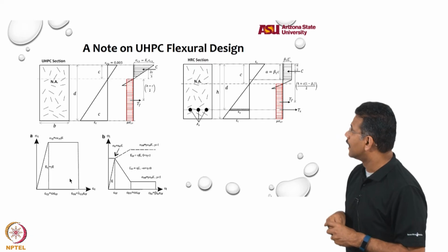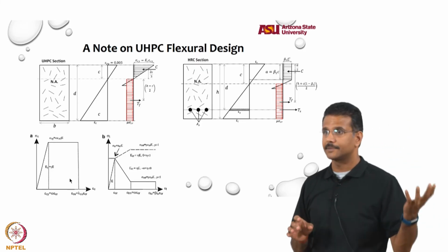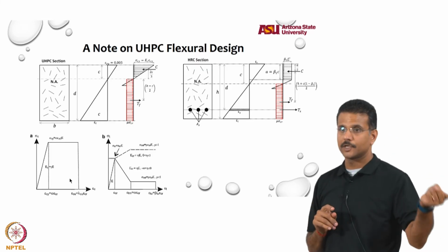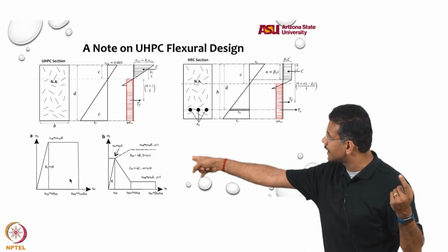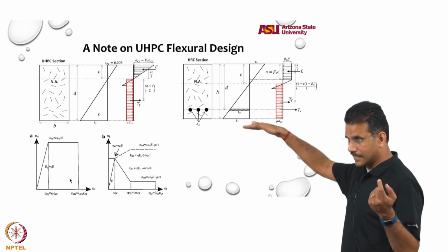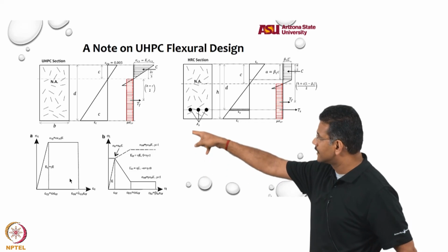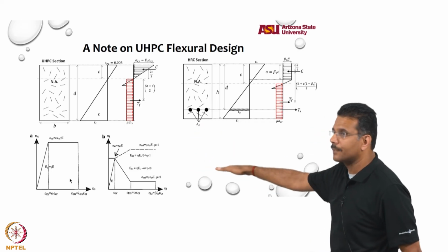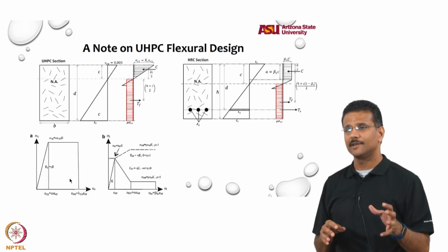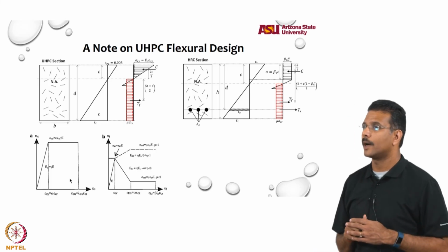Again, in your area below the neutral axis, you have the tensile contribution of steel, which is area of steel times the yield stress of steel, A_s f_y, plus the tensile contribution of the fiber reinforced concrete, for which you use a constitutive model for compression and tension. You can see that there. The constitutive model for compression is a bilinear curve, increasing compression, elastic, plastic, whereas for tension it is a trilinear curve where you have an increase in tensile stress, a drop, and then a plastic region in the tensile zone, and you have different parameters. So, now with this you can start to design your sections much more efficiently and much more economically, so that you are using quite a bit of the advantage of concrete.